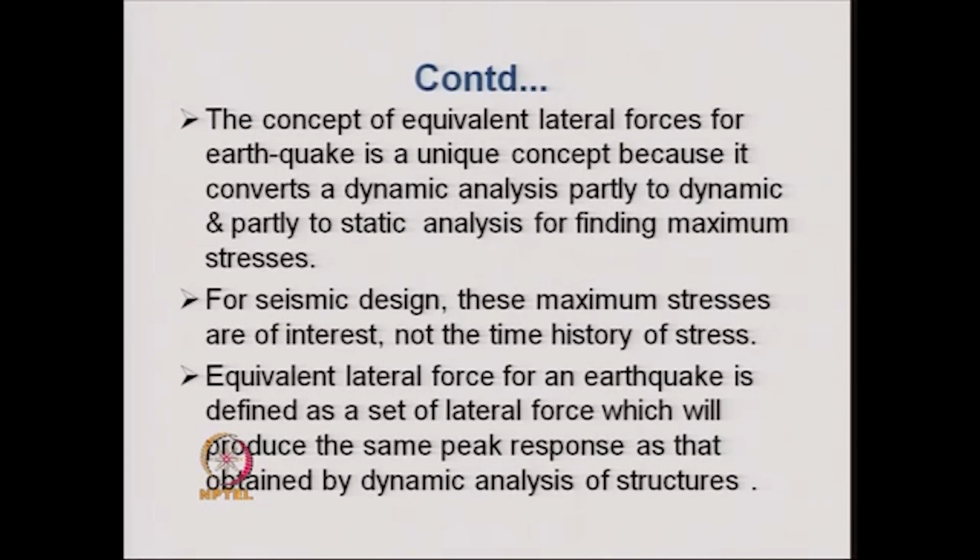Once the mode shapes and frequencies of the structure are known, then the rest of the analysis is a static analysis, and therefore it is called partly a dynamic analysis, partly a static analysis.